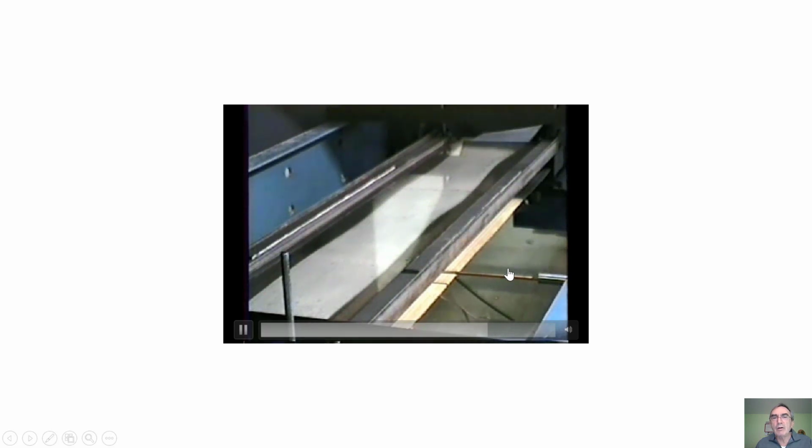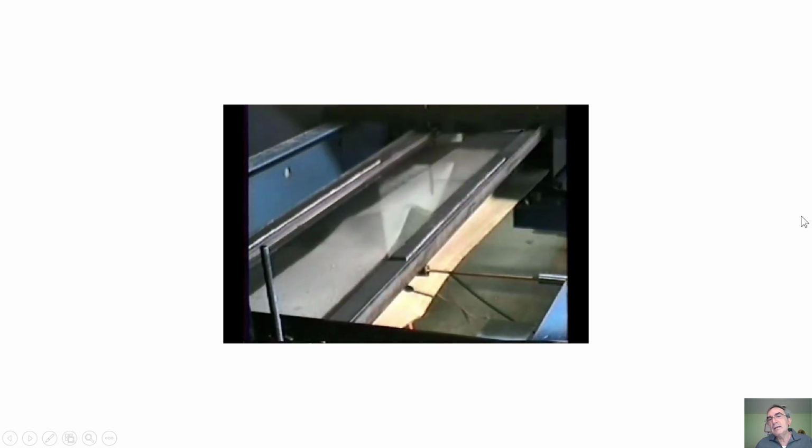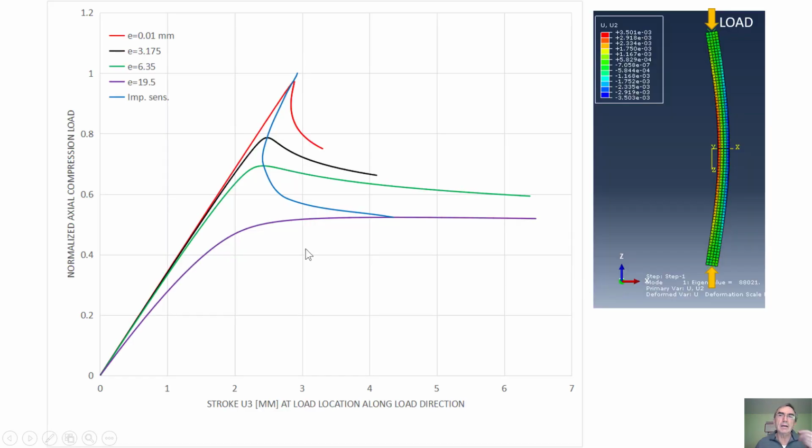And this waviness is going to combine with this Euler mode, which is hard to keep track of because that will be this distance over here. And now it magnifies on one side, just like in the simulation. And then, of course, it's catastrophic, and we broke the column. So now that we have seen the movies, we can use simulation to get more insight into this problem.